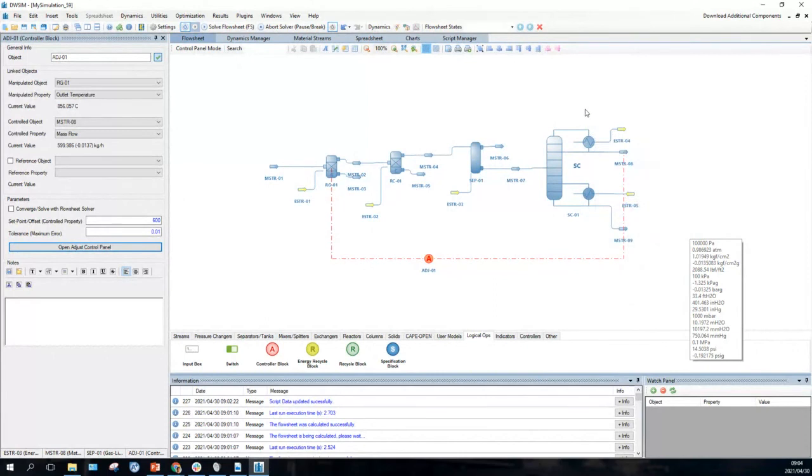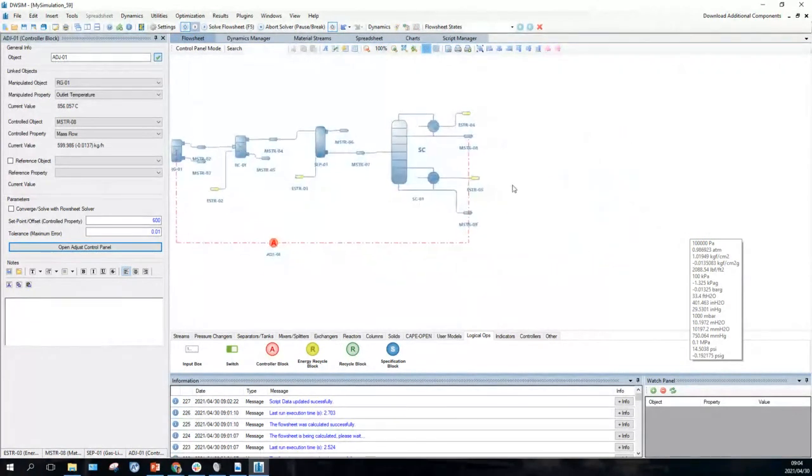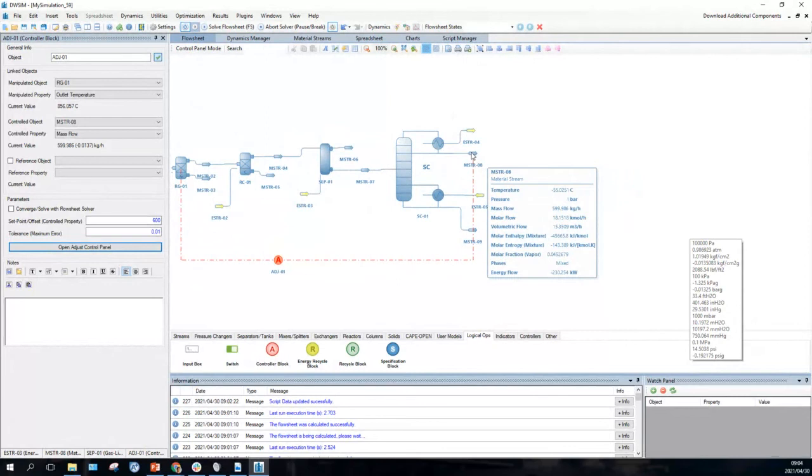You should have a line coming up there with the vapor coming off. It looks like this would be a mixed stream. The phases are mixed. You can see down there at the bottom. Let's move this window this way and then we can see what's going on. The phases of the stream are mixed, so you'd have to put in a gas-liquid separator to actually show them.